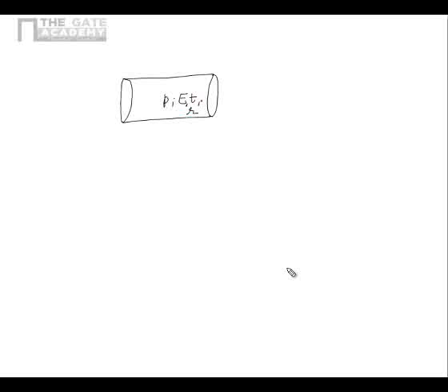Now for this case we know that the hoop stress is PR upon T. This is sigma hoop, and the longitudinal stress is PR upon 2T. This is the longitudinal stress, sigma L.